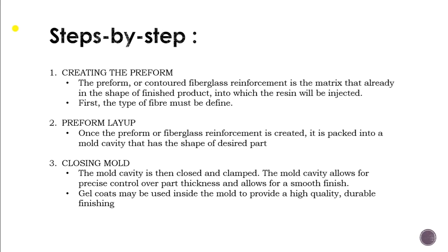Okay. For the first step, it is called creating the preform. The preform or contoured fiberglass reinforcement is the matrix that is already in the shape of the finished product, into which the resin will be injected. First, the type of fiber must be defined.